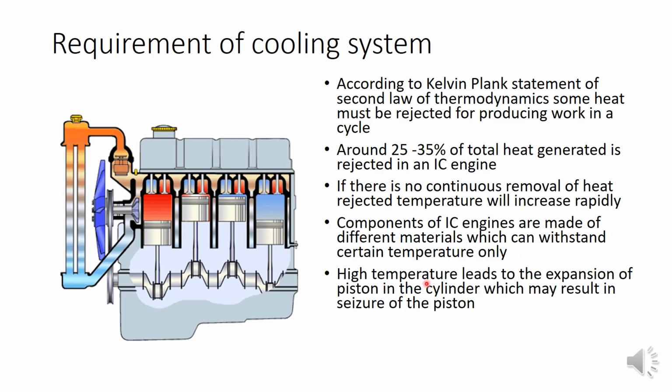It will result in erosion of the component, and even high temperature leads to expansion of the piston. That is another problem. The piston is made of aluminum alloy, so if the temperature increases beyond a certain value, it will expand. What will happen if the piston expands? It will seize in the cylinder walls.